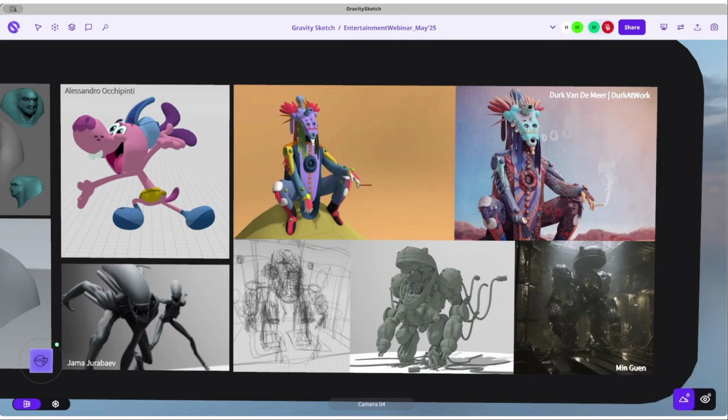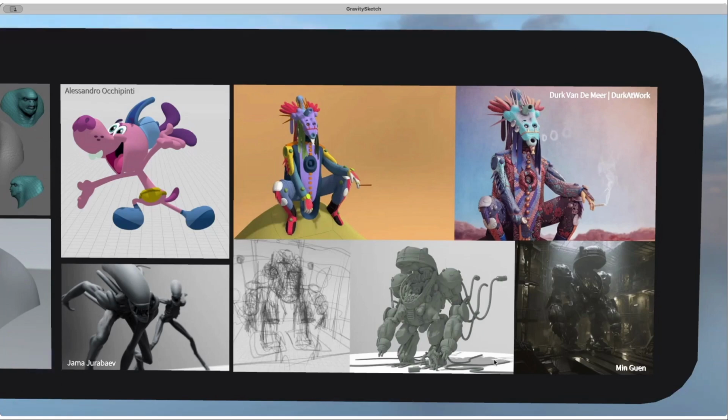Yeah, absolutely. GS is pretty interesting in the way that it handles those rigs. In this case, I exported as a .blend file from Gravity Sketch to Blender. The reason I did that is that when you export as a blend, we actually create modifiers that are aligned to what you're seeing in Gravity Sketch. So if you have a mirrored object, when you export that .blend file and open it in Blender, it shows as an active modifier. You no longer have to go through that FBX issue of exporting and then reapplying modifiers and processing the file.